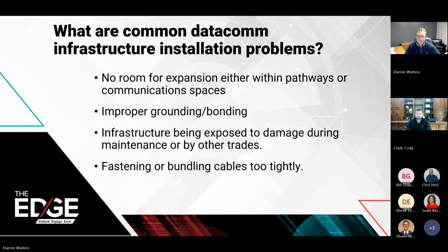Infrastructure: fastening or bundling cables too tight is a common problem, and it's super important when we start talking about 6A and some of the PoE things. I've seen installations where, to the naked eye, it might look really nice. They've got all the cable bundles dressed in there, and they've just got the squeeze put on them with some tie wraps. Once you do that about 30, 40, 50 times as it leaves the equipment room, it can definitely cause some issues and some heat and some alien crosstalk and interference. So that's one thing we want to look for too.